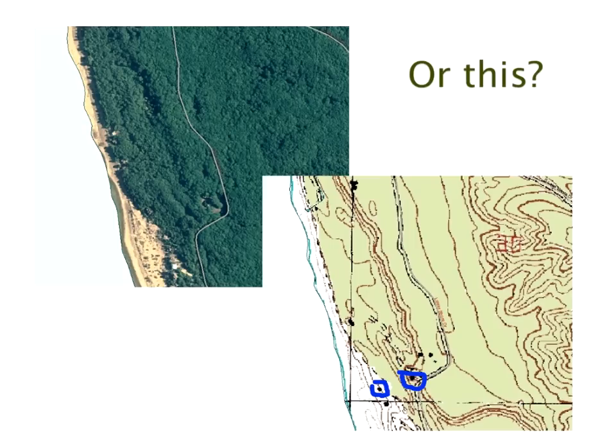But I can give you a quick cook's tour of what you're looking at here. These are high bluffs overlooking Lake Michigan, and subsurface drip dispersal has been used successfully in this jurisdiction for some time, because people buy property here because of the amazing views, the beautiful ridge lines, the amazing tree coverage. You can see the contour line on this particular map. Obviously, if you're trying to put a system in here, you really don't want to be taking down trees. So back to you.